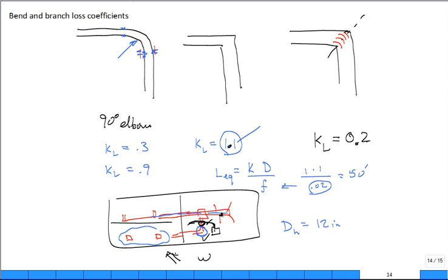They need to dump, typically you basically give so many CFM per square foot of living space. But if you're having the west side in any glass, you need more CFM per square foot of cold air. So all of this hopefully makes it more real to you. Put in little turning vanes. They're not that expensive. Just put them in. It'll help. Also, if they don't put in the turning vanes, how is it going to separate?